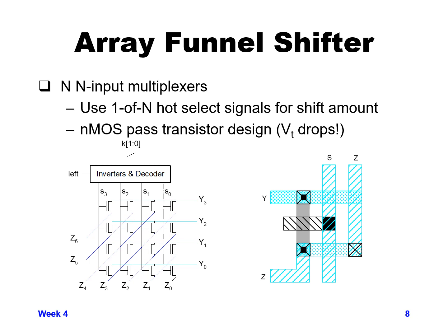So for the top row, we're either going to be selecting Z6, 5, 4, or 3 to go out on the Y3 output. And then the second row, we're going to be choosing either Z5, 4, 3, or 2 to go out on Y2. And that all depends on which select is being chosen. So selects 0, 1, 2, and 3 are selecting 4-to-1 muxes, and then there's 4 rows of 4-to-1 muxes. So that's the N number of N input multiplexers.